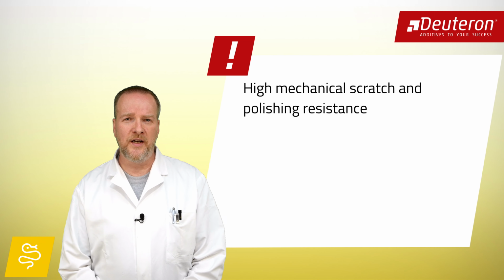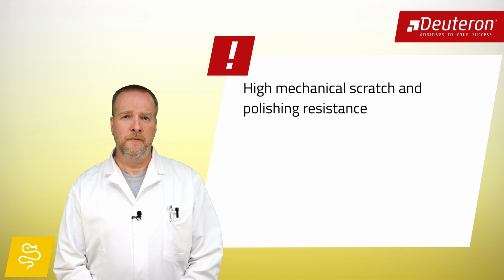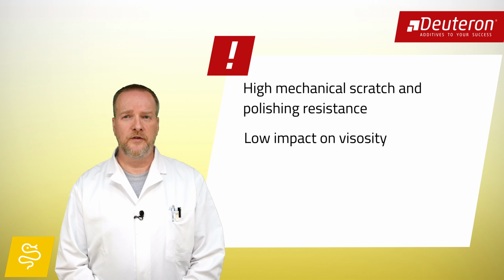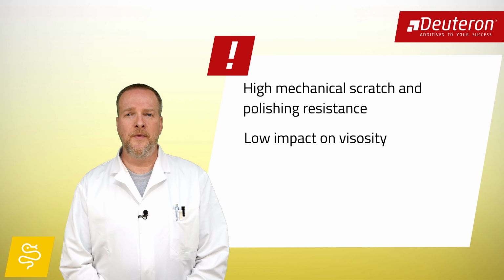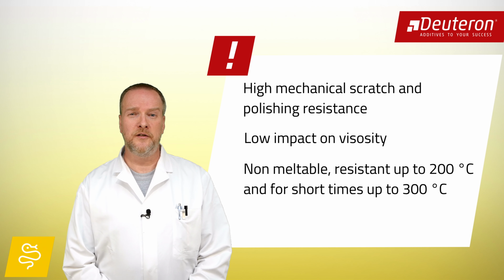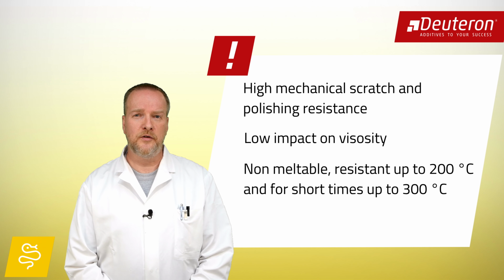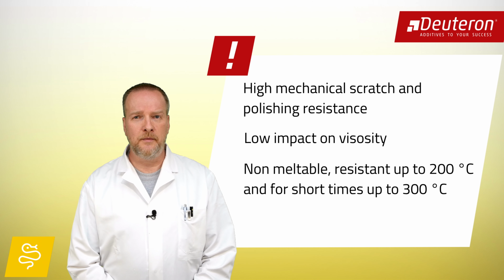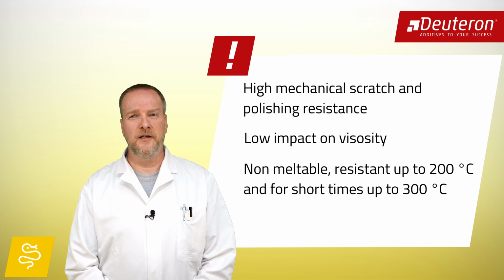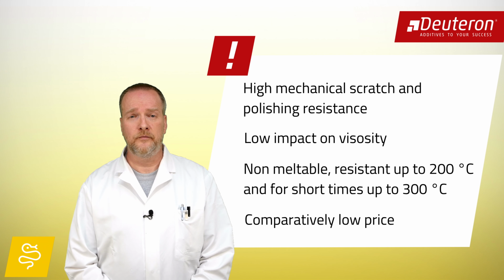The main advantages are high mechanical scratch and polishing resistance, very low influence on the viscosity, they have no melting point, the temperature resistance is up to over 200 degrees Celsius and for short-term temperatures up to over 300 degrees Celsius. And they have a comparatively low price level.